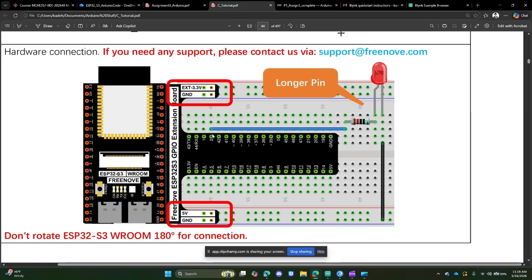The only thing that will change is after part 1, I will be taking this wire from pin 2, going to pin 1. That way, the onboard blue LED at IO2 right here is separated from the red LED, which is at pin 1. I did this because I wanted the blue LED that's built in to be a signal that everything's connected and ready to operate. And then the red LED is what I'm actually controlling in part 2 and 3.